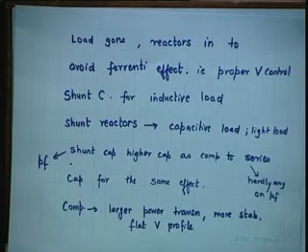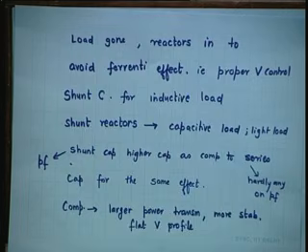Series capacitance or compensation hardly has any effect on power factor, whereas shunt, yes, it improves the power factor. And you have seen in that example how it gets improved from 0.707 to 0.94 or something like that. Compensation is very much needed for larger power transmission, since transmission capability increases, which we need all the time, because at times we have generation but no transmission facility.